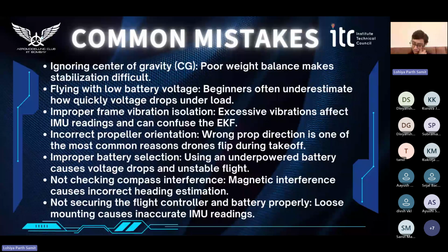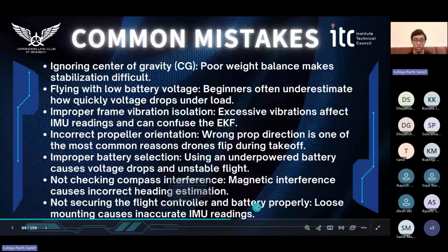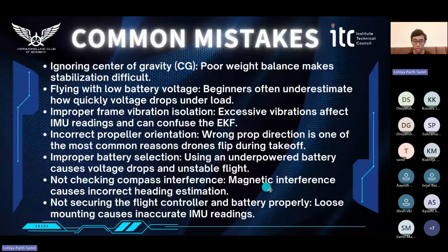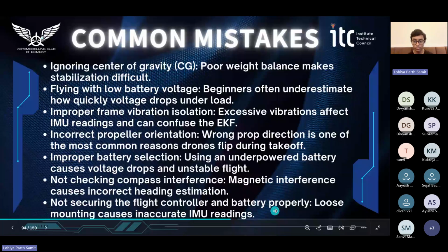The next and the most important one is not securing the flight controller and the battery properly. Loose mounting can cause inaccurate IMU readings that can lead to confusion in the EKF. And a good way to properly mount your batteries and flight controllers would be using a Velcro system.